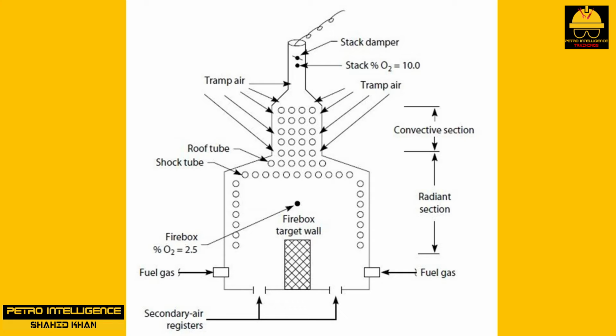Unfortunately, many heaters have oxygen sensors in the stack and not in the firebox. An oxygen sensor in the firebox may provide a useful guide, as we mentioned earlier, although it is not actually needed to run the heater efficiently.